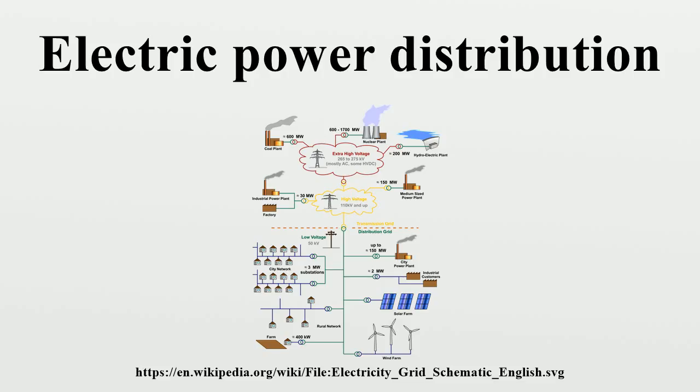Characteristics of the supply given to customers are generally mandated by contract between the supplier and customer. Variables of the supply include AC or DC. Virtually all public electricity supplies are AC today. Users of large amounts of DC power such as some electric railways, telephone exchanges and industrial processes such as aluminium smelting usually either operate their own or have adjacent dedicated generating equipment, or use rectifiers to derive DC from the public AC supply. Nominal voltage and tolerance.